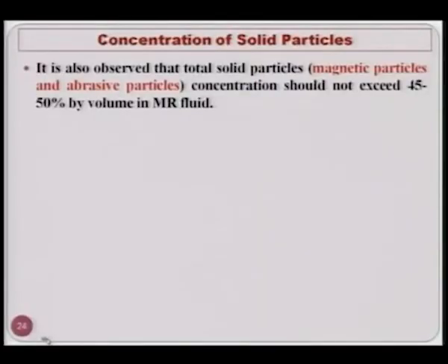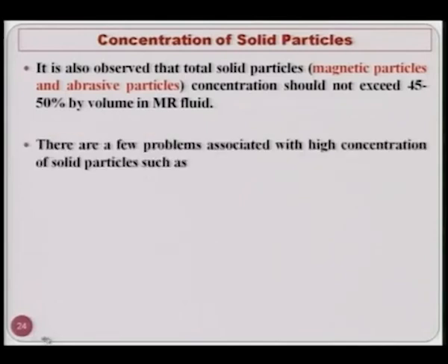It is also observed that total solid particles, which includes magnetic particles and abrasive particles, concentration should not exceed 45 to 50% by volume in MR fluid, because if too much of solid particles are there, then flowability of the medium will be reduced.